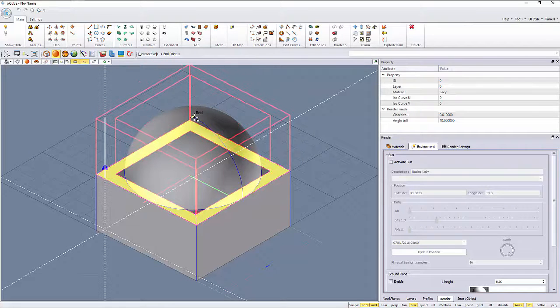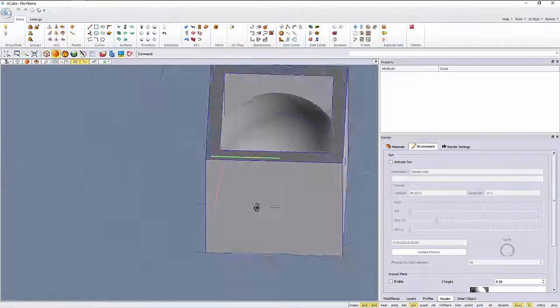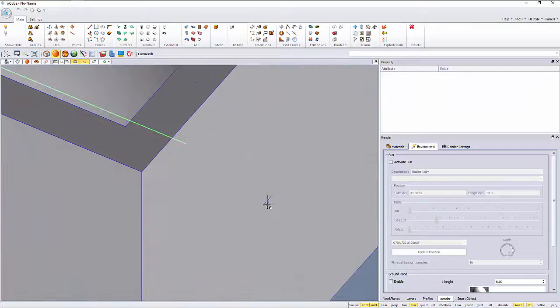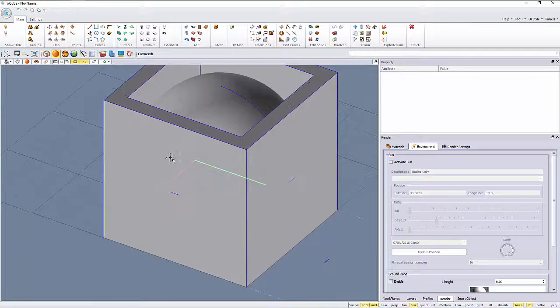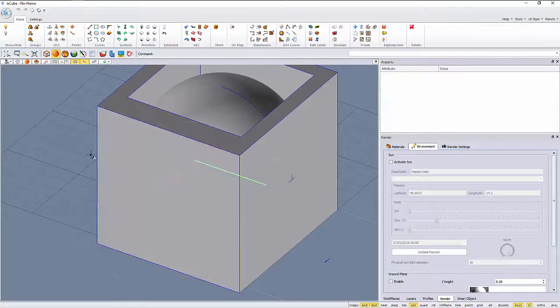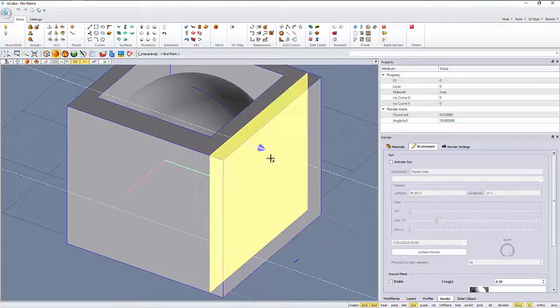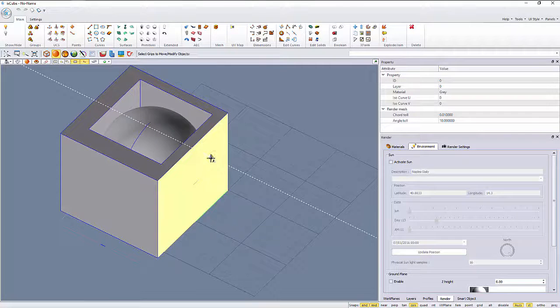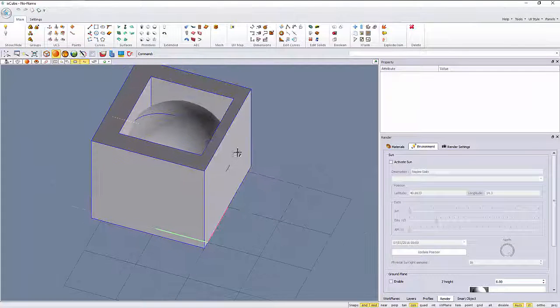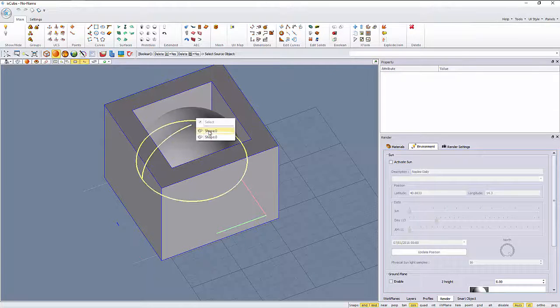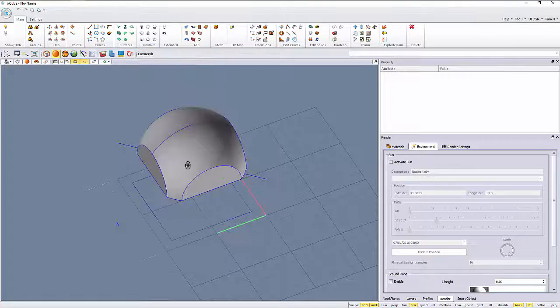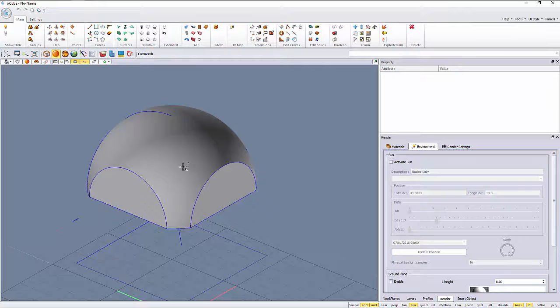Let's click on the edges of this, extrude. You see now that this edge is tangent with the dome. That's not a good thing to do when you have to do Boolean operations. It's better that they are like that. So I would pull off a little bit these like that, and yes, go to Boolean, subtract from this dome, take off this one. So we have sliced the dome like that.